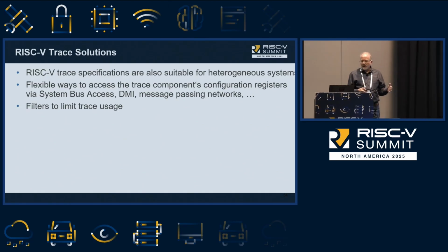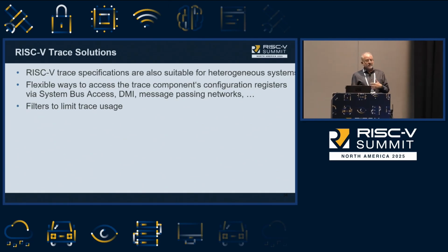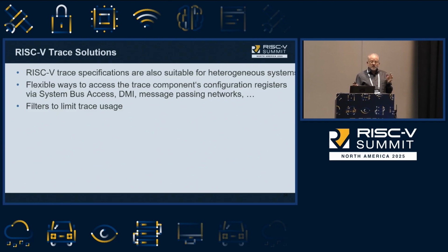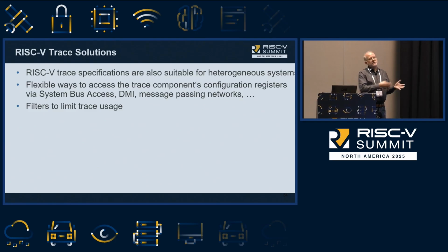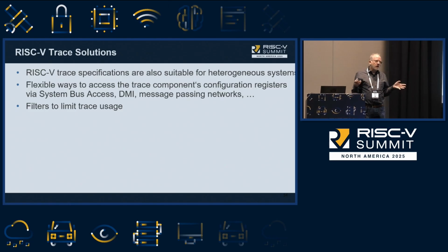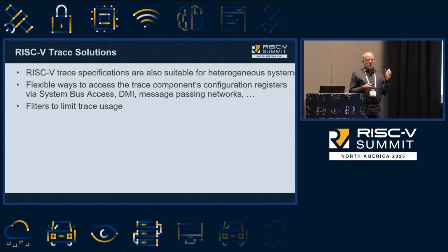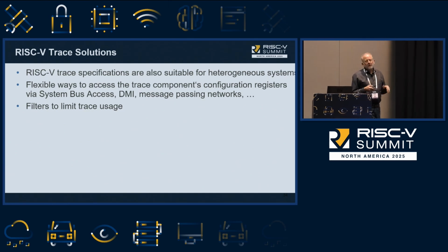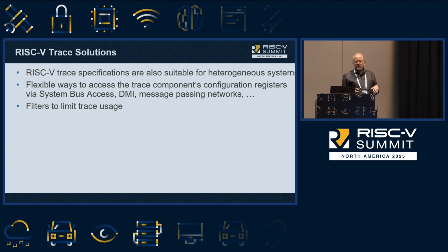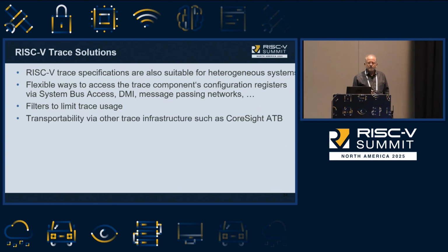this is where you get your value add. One of the things that comes up, and somebody was asking, you can actually filter trace. So I guess getting down in the weeds a little bit, one of the issues you have with trace is there's just a lot of stuff that can come out of your application or real-time cores. You might want to narrow that focus. So I only want to look at the needles, not the hay. It also limits your bandwidth, and that may allow you to be successful.